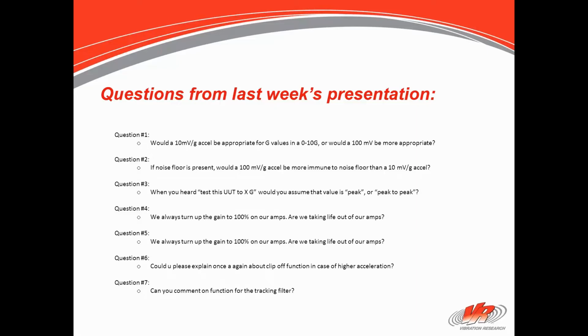So if you're running a test and your product has a 400 hertz resonance in it, and you sweep and you're controlling without a tracking filter, you think you hit it with 400 hertz, but you never did. So if your intent was to find resonances that may occur at 400 hertz, guess what? You never excited them. You're never going to break them with a test like that.